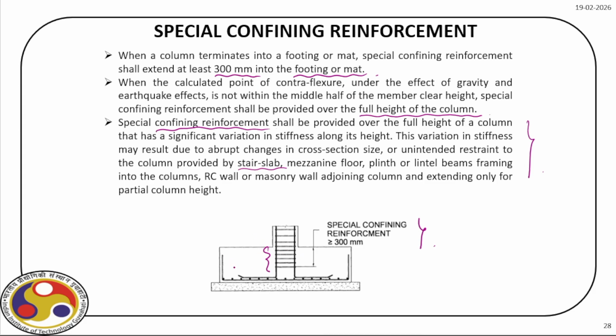Now, for this footing, again, recall, we have to check the development length of these bars, these are dowels. And then we have to have additional confinement so that particularly during an earthquake, when there is shaking here at the base and the column also sways on either side, there should be a proper load transfer between the column and the footing, and that will only be possible through proper confining of concrete so that the steel rebars are intact and can experience large deformation without buckling at this critical location, right?